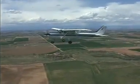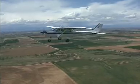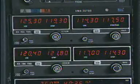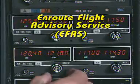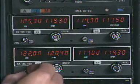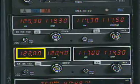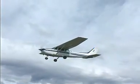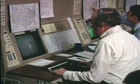Now that you've discovered where to obtain weather information prior to flight, let's explore how you can get updated weather information while airborne. One of the best sources of en route weather is En route Flight Advisory Service, or EFAS, also known as FlightWatch. This service is available from selected flight service stations. The frequency for FlightWatch is 122.0. After giving the EFAS specialist the details concerning your flight and your request, the briefer relays the latest weather information.